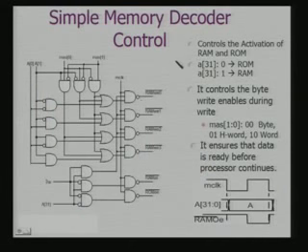So, the interesting thing to note is I control activation of RAM and ROM. So, the A31 bit is typically being used for this purpose. So, if you see here, the A31 bit is being used for selecting RAM or ROM, obviously because they are located at two different addresses. They have to be located at two distinct partitions.